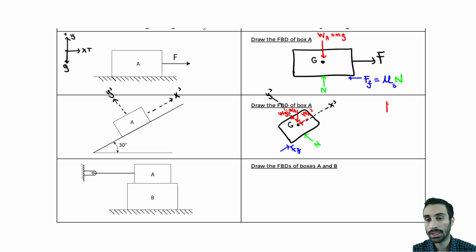And if I draw that on the side here, it looks like this. You have the weight W, which is the magnitude. You have wx prime, and you have wy prime. And now, we know here, this is 30 degrees. Now, the tricky thing is, where is the angle here? Is it here, or is it going to be here? Or in other words, is 30 degrees here, or is it here? I'll tell you right off the bat, it's going to be here. 30 degrees is always with your y component and the magnitude of the weight. Always, when you have an incline.